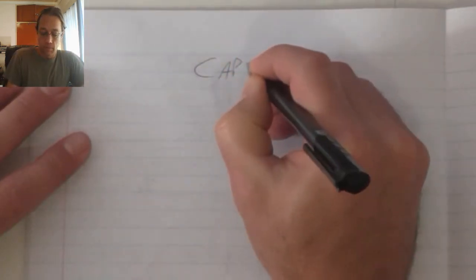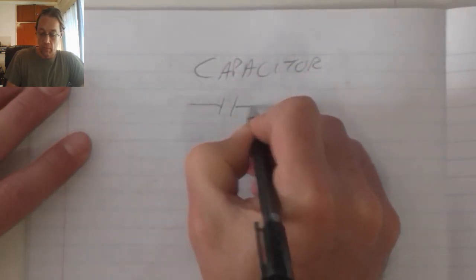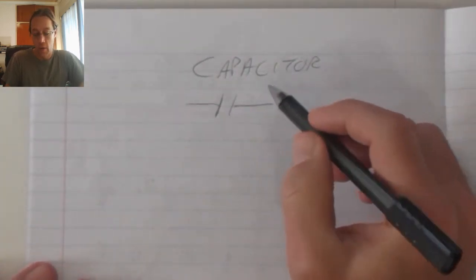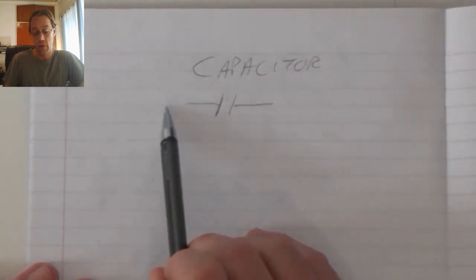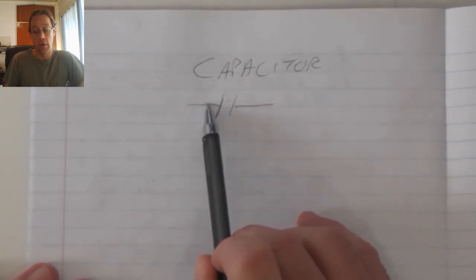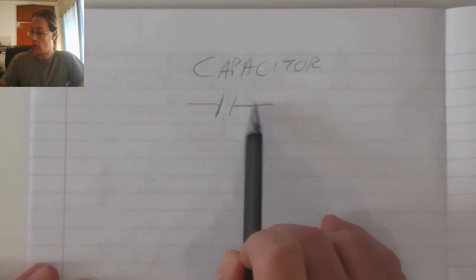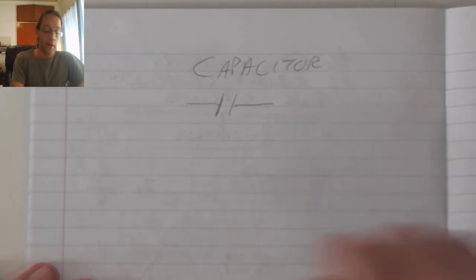The capacitor has an infinite resistance due to the dielectric in the middle, but when we supply voltage to the capacitor, current flow is at a maximum. As that voltage increases, the current will decrease. So as a result, the capacitor also develops a reactance.